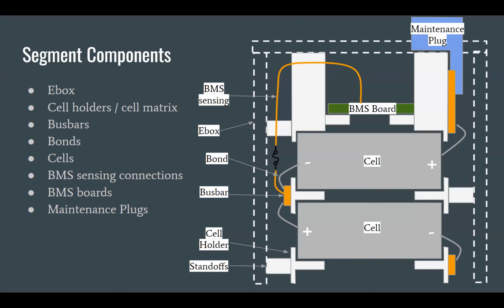In particular, our bus bars are nickel-plated copper, but you could also do something like an aluminum bus bar, or if you wanted to be really inefficient, you could make steel bus bars. No reason to do that. Yeah, so those are just the pieces of metal that make sure that if I connect these cells to these cells, their voltages are all tied together in parallel.